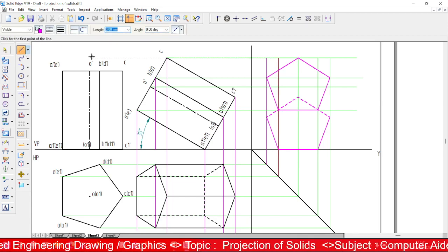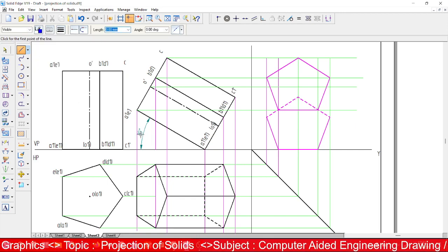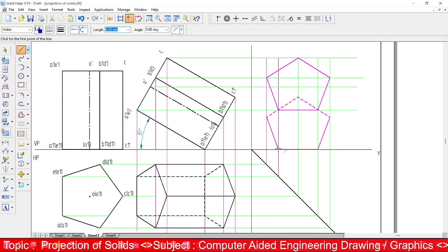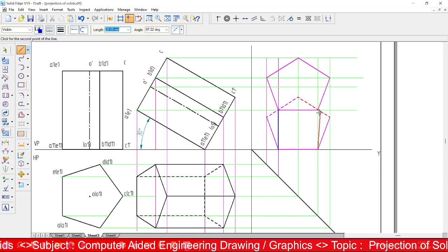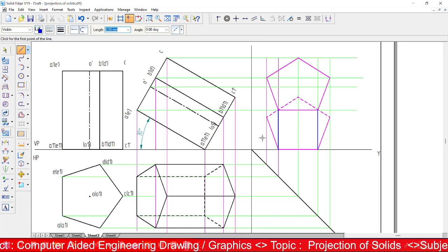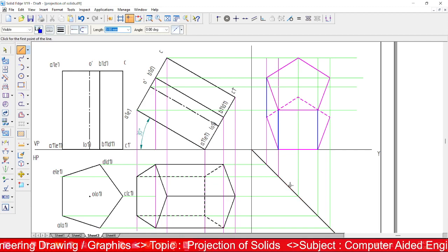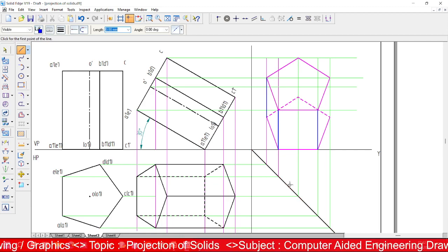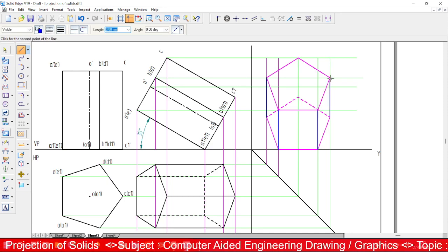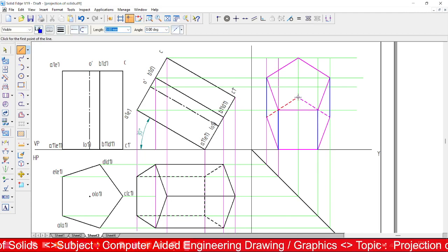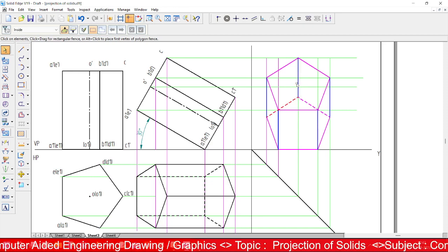Now let us join the first clearly visible portion here. So as you are going to look from this side, this rectangular surface is clearly visible. Let us mark here. Now let us mark this point, this edge, that is what edge D1 D. So here you got edge B1B. Now hidden edge is C1 C here. C1 C edge is hidden.